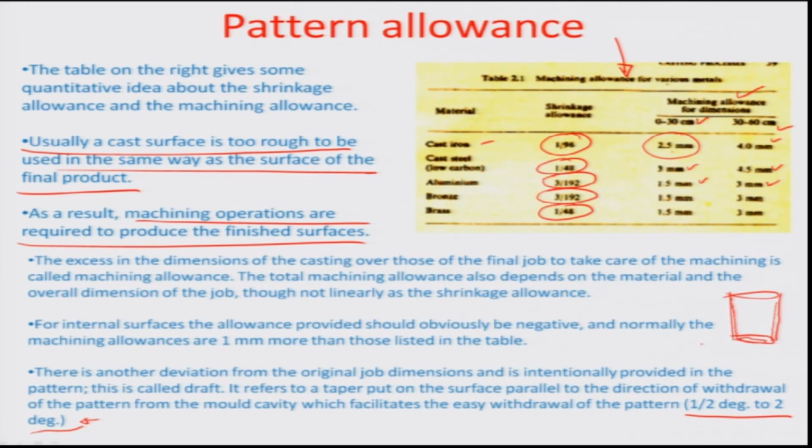We will talk more in the next module about how we further design the mold, and how we design the runner and the riser, which are the two most important things to ensure that the metal flows well into the cavity before it freezes, and also rises on the other side to indicate that the cavity is full. So, thank you as of now.